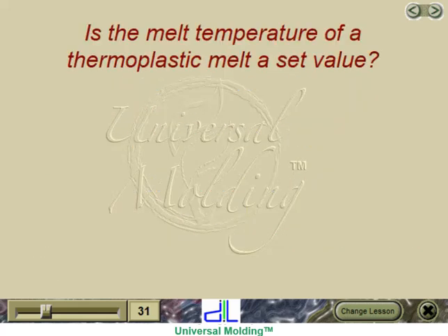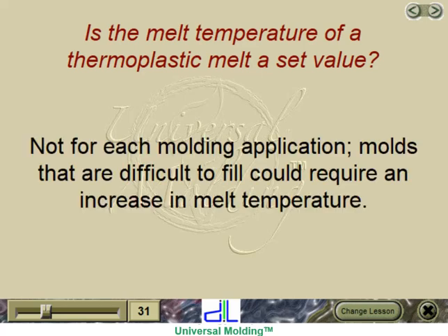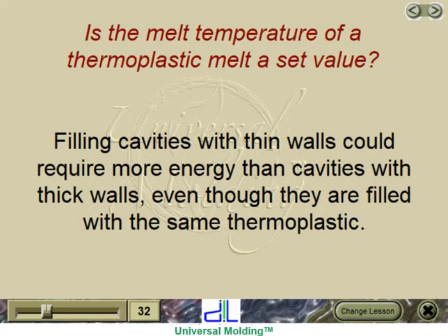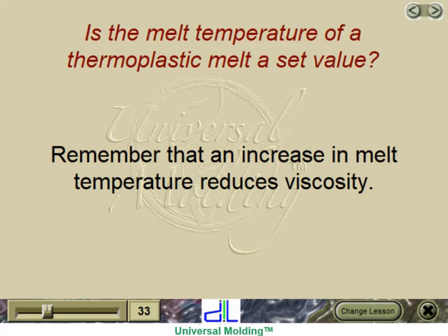Is the melt temperature of a thermoplastic melt a set value? Not for each molding application. Molds that are difficult to fill could require an increase in melt temperature. Filling cavities with thin walls could require more energy than cavities with thick walls, even though they are filled with the same thermoplastic. Remember that an increase in melt temperature reduces viscosity.